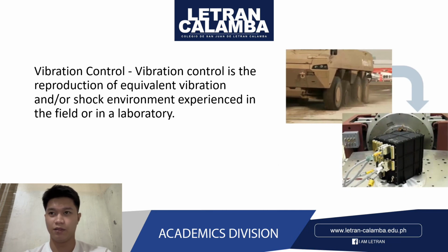on a shaker table. So the purpose of environmental testing is to expose the design flaws of a product in controlled conditions. So we want to reduce the chance of field failure in real-life operating conditions. During the test, if we break a part, we might ask ourselves, did we overtest the part? If we don't break the part, we ask ourselves if we undertested the part. If we're going to use an established standard, such as a military standard, we have to ask if the standard is relevant to the type of operating condition that the part might actually experience.